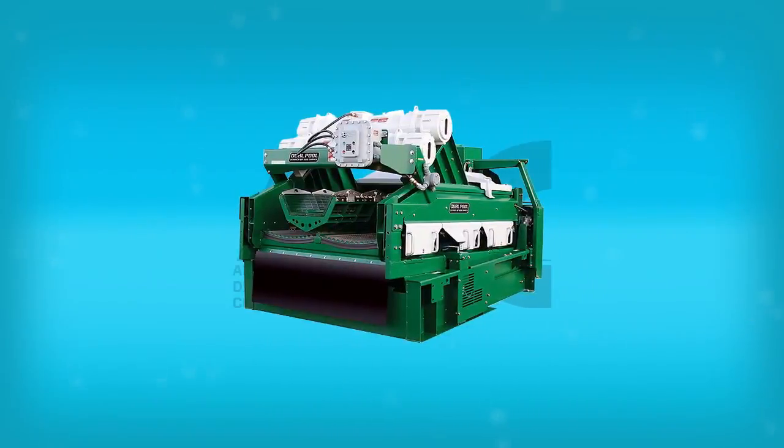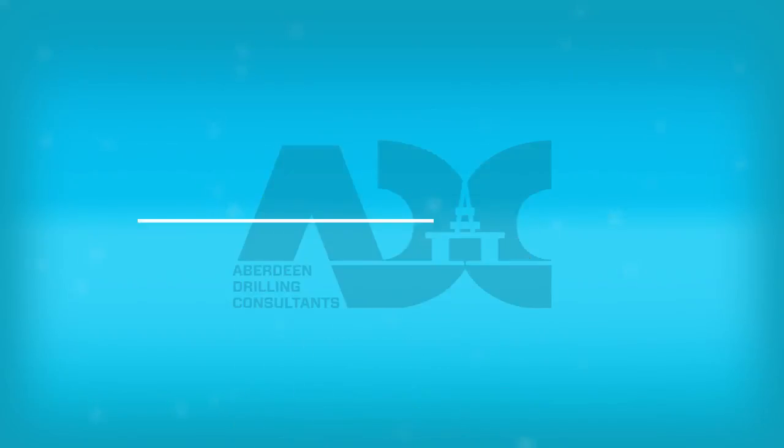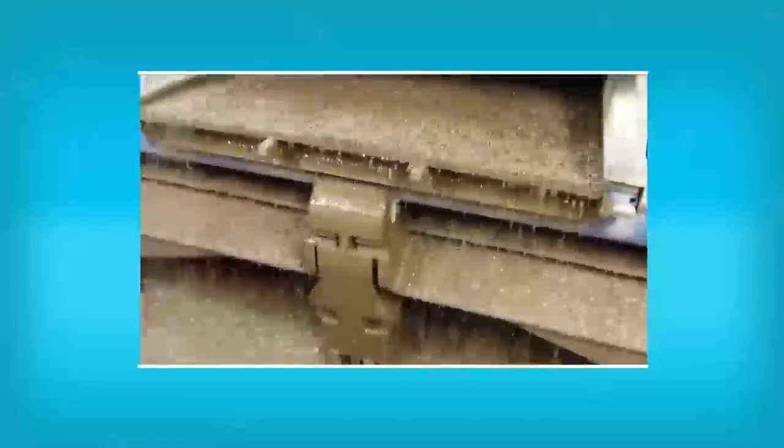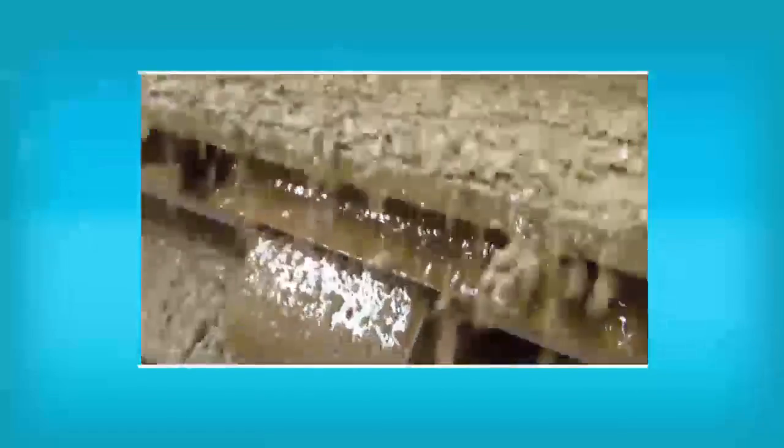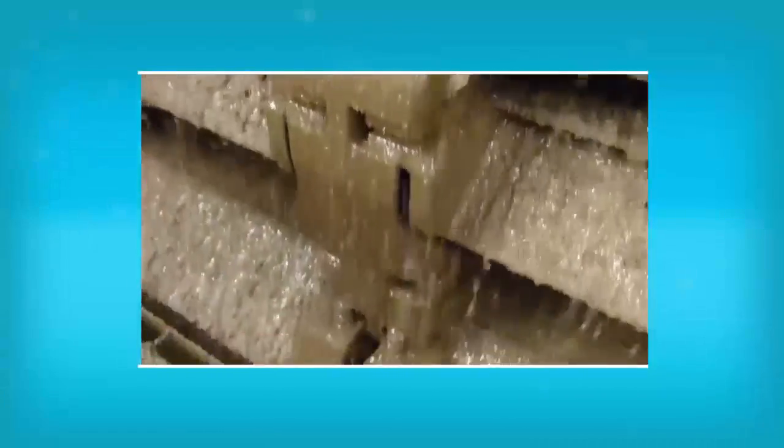When the fluid reaches the surface, it flows down the flow line and onto the shale shakers. The shale shakers have vibrating screens. The fluid flows through the screens and the drill cuttings are collected. If the mud is water-based, the cuttings may be discharged overboard. However, if the mud is oil-based, the cuttings are stored in containers to be transported ashore to be processed.